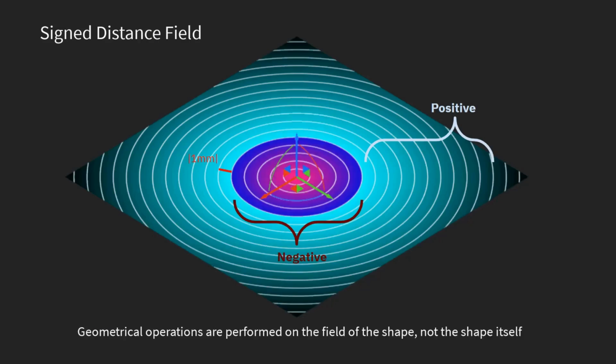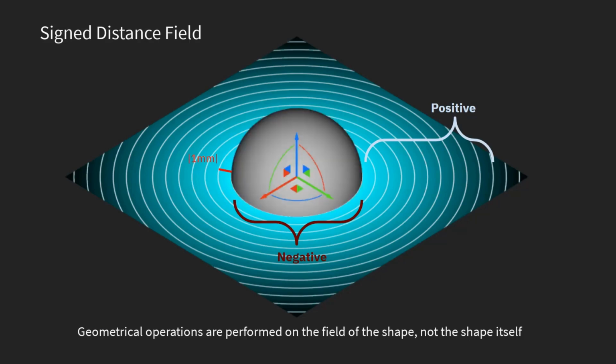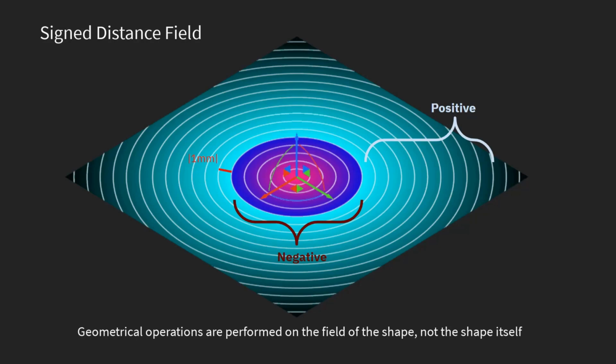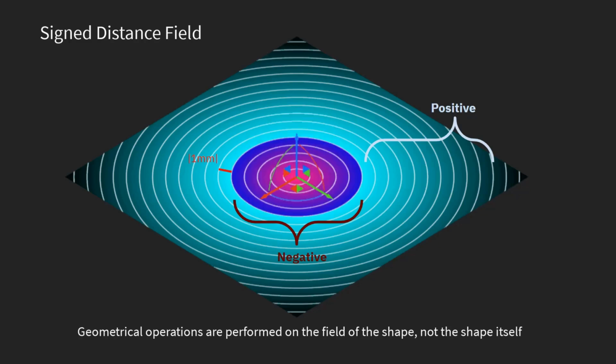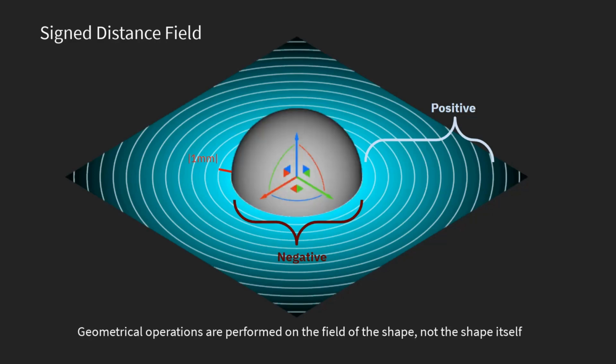What drives the geometry in nTopology is the distance field, where at every point in all directions in the infinite 3D space, there is a distance value that describes how far away that point is from the boundary of the geometry. These values are the outputs of the mathematical equation that describes that geometry. And we use the term implicit to mean that the values of this distance field are negative where it is inside a solid body, and positive where it is outside of this body.